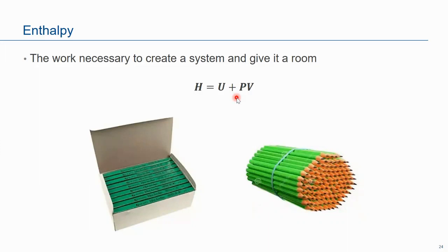And to occupy a volume V, the gas has to do some kind of work, which we call displacement work, and it's equal to PV, in order to occupy that space by pushing the atmosphere out of that volume. The atmosphere is like the rubber band, always applying a compressive pressure on the gas.